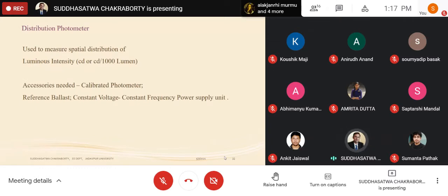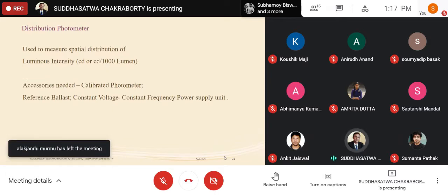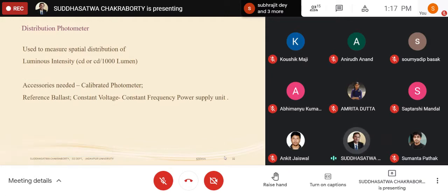With integrating sphere-based measurement, the only drawback is that we should always have a calibrated lamp, which we call a luminous flux transfer standard lamp. So it may be possible that you don't have this one. But in the other way, if you are going by the direct method or zonal lumen method, where you are dividing the entire space into small zones, that type of measurement has only one problem. You should have a very good calibrated sensor. That is essential for all types of measurements.